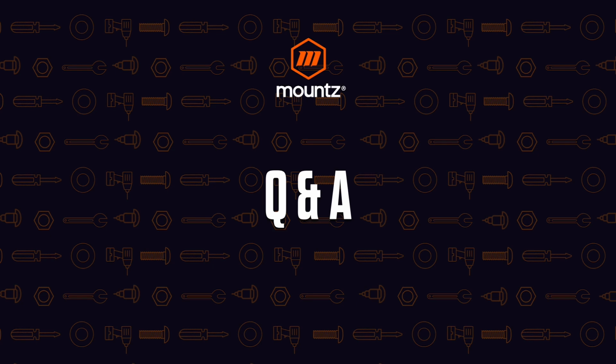All right, Dave. Another question we had is, how do you determine the appropriate torque to be applied to a specific fastener? So again, that is going to be very, very part specific. You'd want to do some destructive tests if you are having issues with a particular joint that's failing. Now, if it's failing because the parts are vibrating loose, you may have a situation where you're not getting enough clamp force.